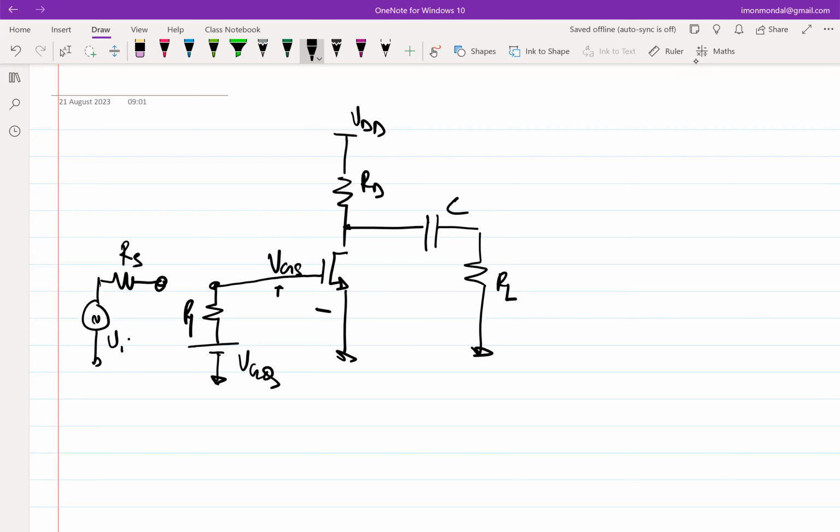Right. So if VGS had to be higher than VDD, then our linear region transistor probably wouldn't have been biased in linear region, right? Because ultimately you have to honor the fact that the drain is at least not below one threshold voltage below the gate, right? Otherwise, it would have been a problem.